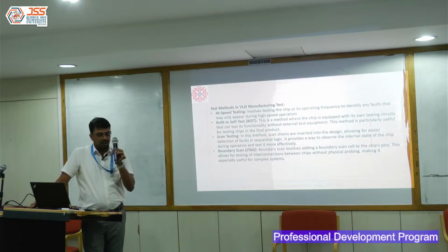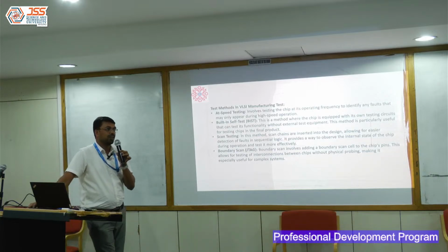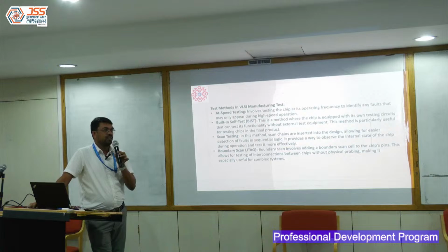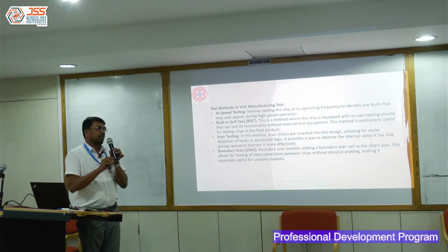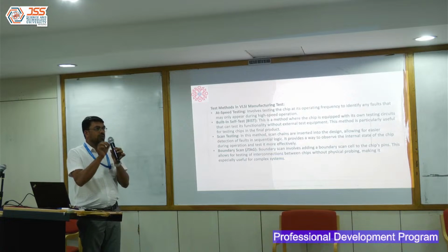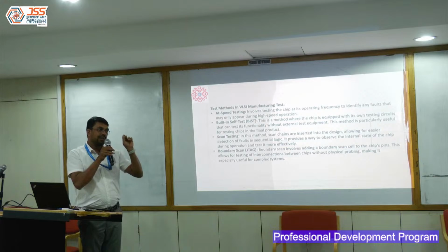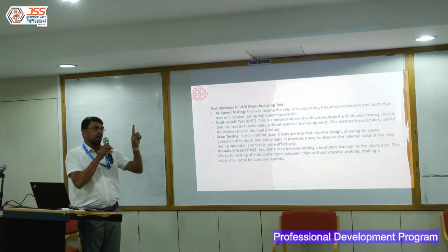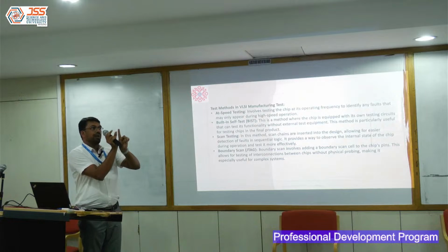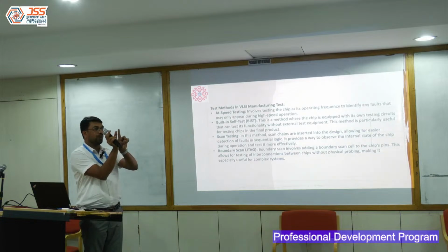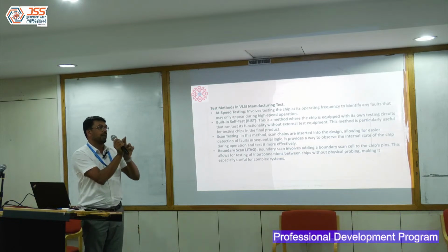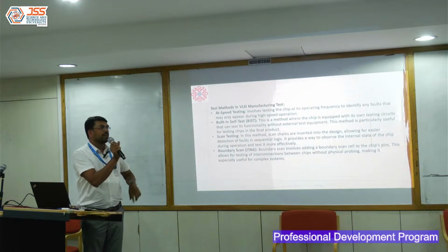For hold, let's go back to the basic definition of hold. The basic definition says it's the minimum amount of time the data has to be stable after the appearance of clock, right? So if I'm increasing or decreasing the frequency, I'm just moving the clock edge. As per my definition, the hold is going to be after the appearance of the clock edge. So if you move the edge, it is not going to help, because your requirement is also going to move along with that.